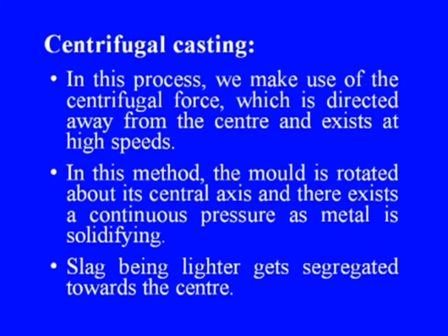In this method, the mold is rotated about its central axis and there exists a continuous pressure as the metal is solidifying. Slag, being lighter, gets segregated towards the center.